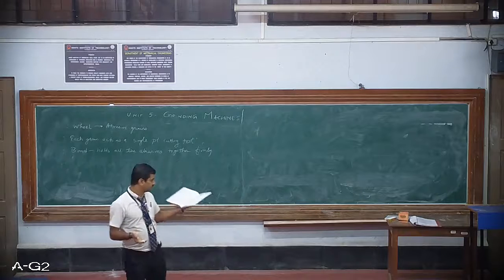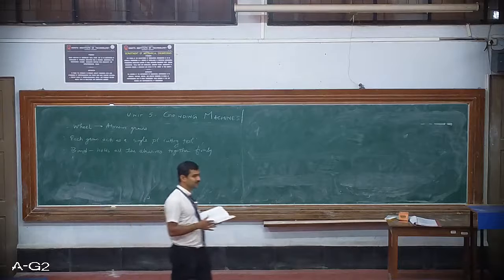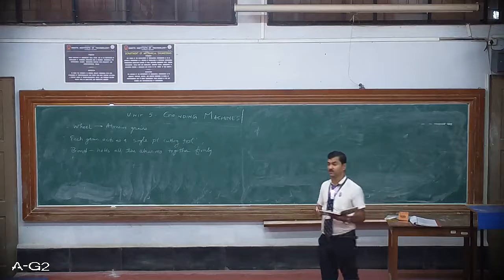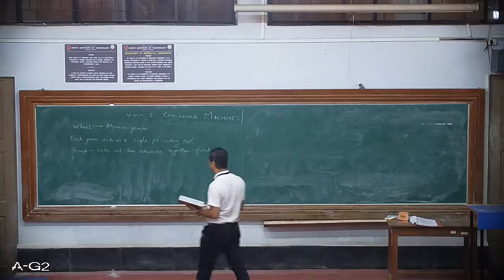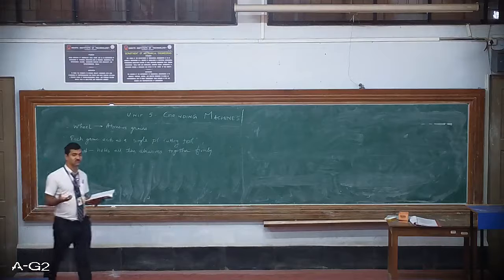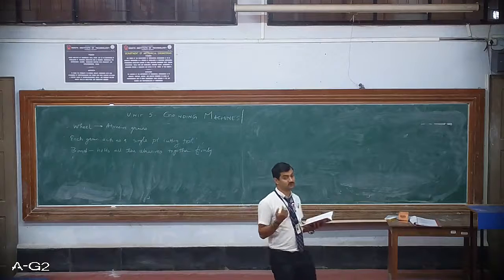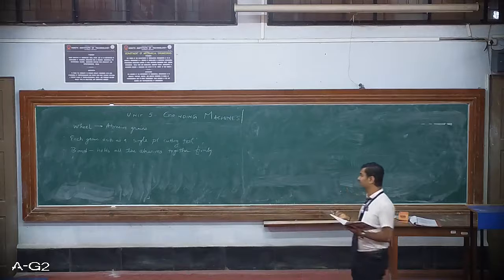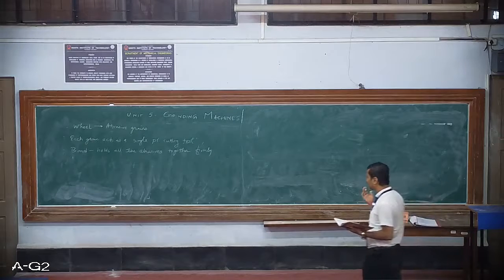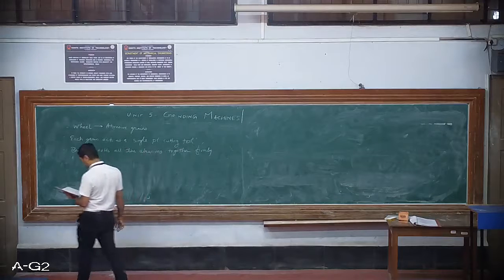I will show you once we switch on to the PPT. You will be able to see the video of that grinder. Of course, you have seen how those abrasive particles, on the rough surface, are stuck onto the surface. They are held firmly. Of course, the bond is very strong. It has to hold all the abrasive particles very firmly, rigidly, because of the force that it has to withstand. One is rotation, another is it has to press against the work. So the bond has to hold all the abrasives together very firmly.